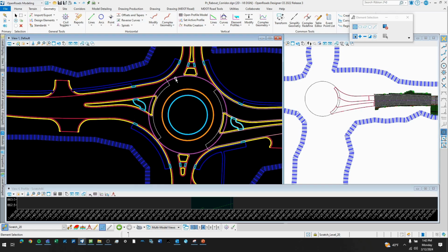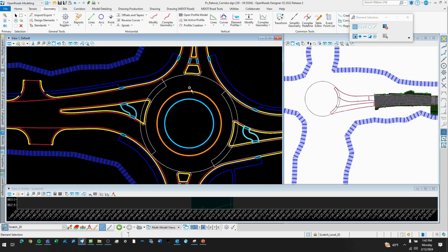I normally map this out on a piece of paper. I'll draw a circle, and in my mind, if it's a 4-leg roundabout, PGL-wise, you have this tie-in here. This is an important piece, where this ties in, and then where the legs meet. So you'd have 1, 2, 3, 4, 5, 6, 7, 8, 9, 10, 11, 12 pieces there that you're really trying to find elevations for.